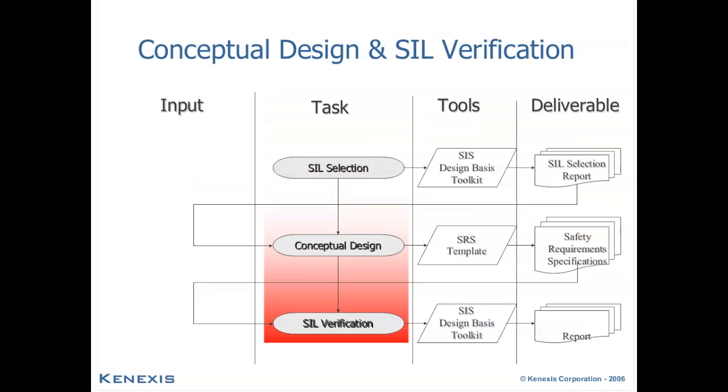We can move, after we've selected the SIL required for each of the safety functions, from the SIL selection step to the conceptual design and SIL verification steps, which really are an iterative loop where we start with a conceptual design, we run it through the SIL verification process, and we may have to iterate a few times to get to a design that meets the SIL targets as determined by SIL verification.